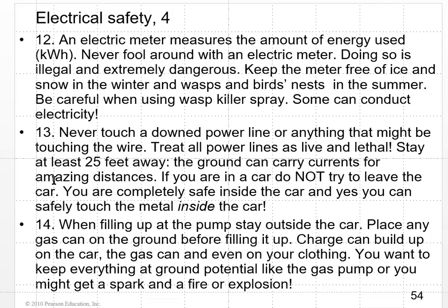You want to get one that does not conduct electricity. Read the label carefully or ask the guy behind the counter at the hardware store. Never touch a down power line or anything that might be touching the wire. Treat all power lines as live and lethal. Stay at least 25 feet away. The ground can carry currents for amazing distances.